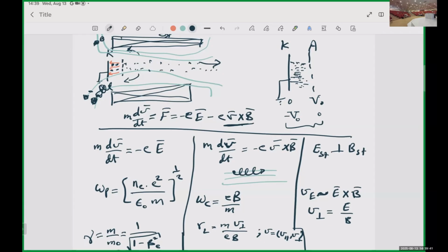But when we go to the waveguide, with one plate and a second plate, either it is going to guide the RF, or you want to generate RF between these two somehow. A slow wave structure is used in this case. It's a similar concept, except that you can't separate the phenomena, because we are trying to extract energy from electrons. That's why I said at the beginning that we combine the diode with the slow wave structure to get the best performance, and we call this the interaction region.